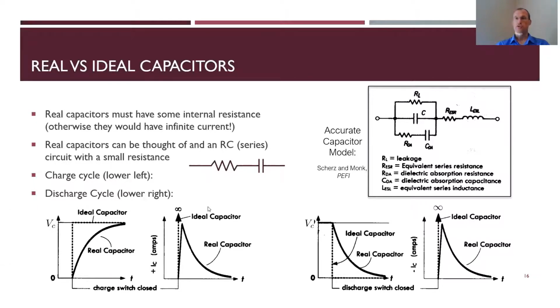Basically, your RC time constant would be 0 because the resistance is 0. And so it would take 0 seconds for that to completely charge. So instantaneously, essentially. The current would be infinite for those 0 seconds until it's fully charged, which again takes 0 seconds.